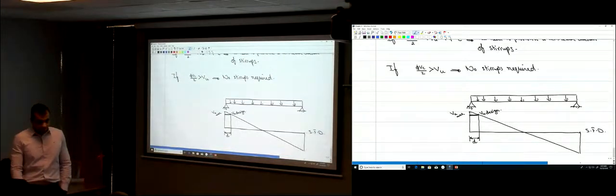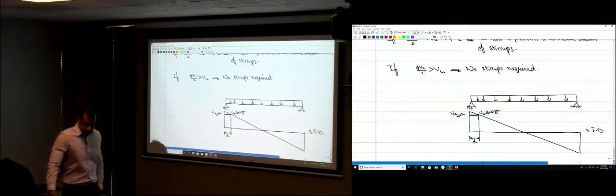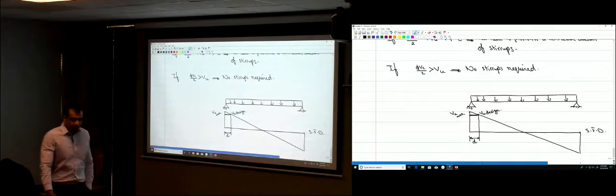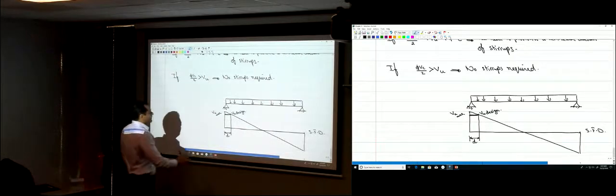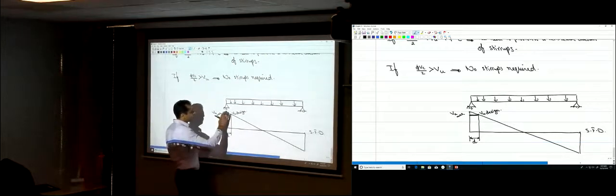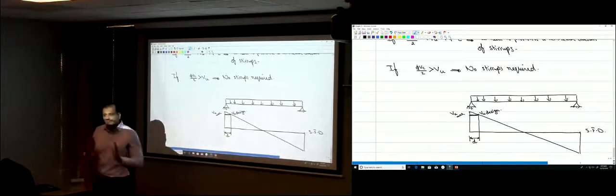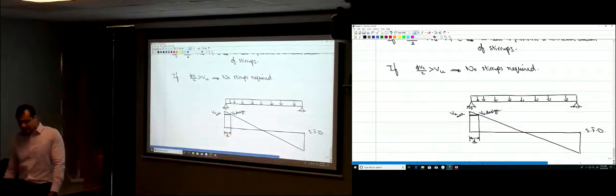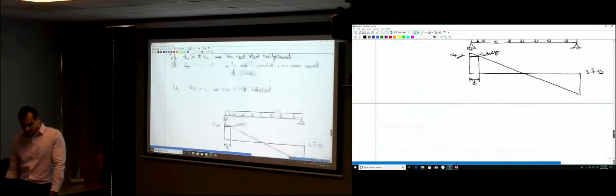Dr. Grubb, why is that? Because when I was doing the FE review, we had a question like where would the shear be the max, and I chose at the end, but the answer was at a distance d from the support. Okay. When you draw this, the maximum shear force is over here, but actually this is not applied on the beam. Let's see why the ACI allows you to move a distance d from the support.